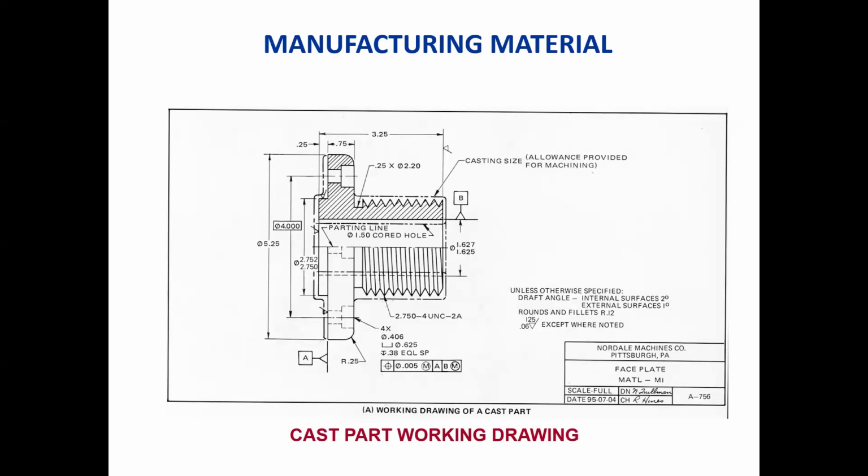So like strengthen the screw area or something? Well, it just keeps you from having the material in there to have to drill it out. Oh, so it just saves on material waste and faster time and all that stuff. Yeah, so it's actually just a block placed in there that makes a void right there. So that's a core. Oh, it comes out whenever you cast it. Yeah.